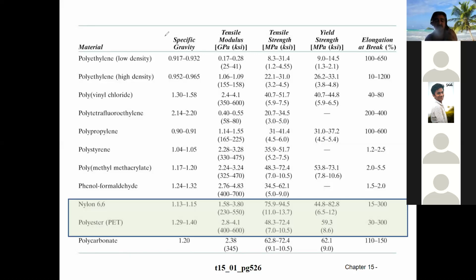The tensile strength is coming from the crystalline part, and the amorphous nature, or the molecular conformations, tells about your yield strength. So molecular conformations like ring structures will give a high yield strength, and crystallinity behavior will give you tensile strength. So this will give some insight about the polymers.